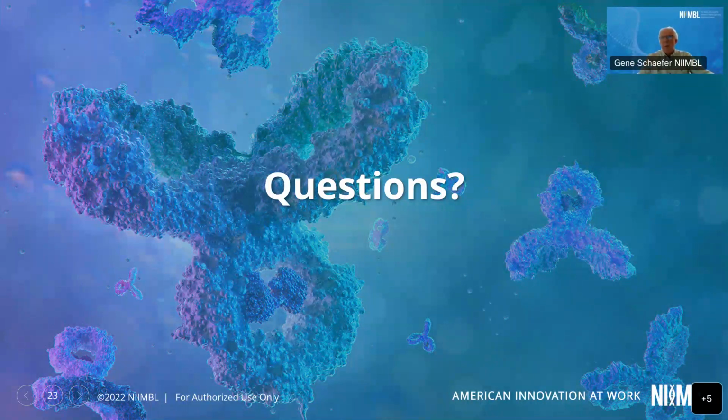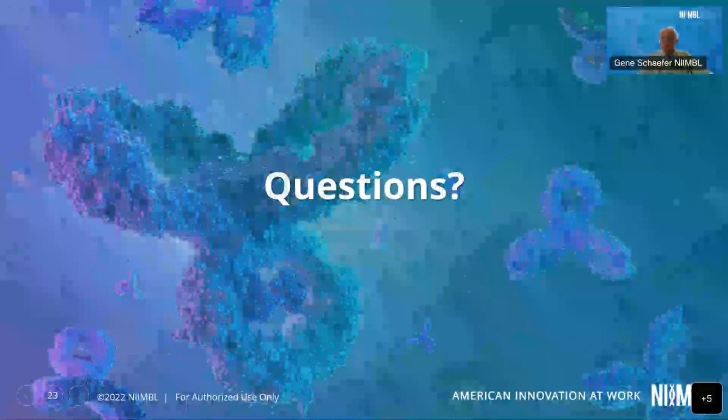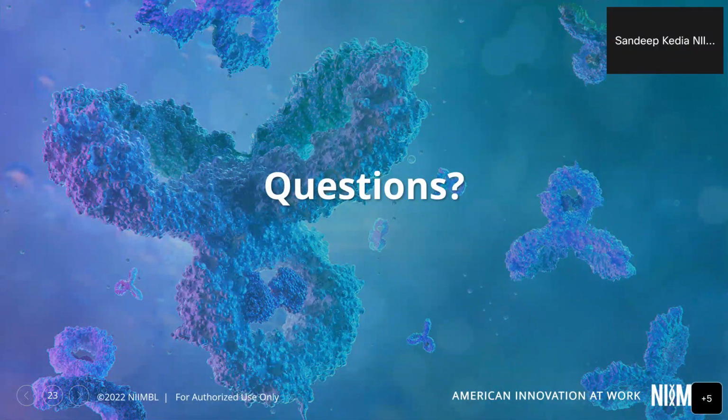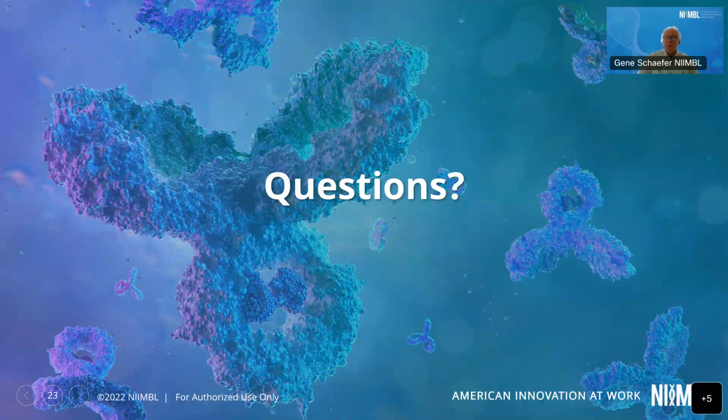And the last point, we did, as I pointed out earlier, look at the other option of just running that as, say, a dual tank alternating mode, where you're essentially running it as a cycled batch operation in the middle of the process. Some of those defaults, similar to cycling between two columns, some of those approaches are good gateways into a more continuous and integrated downstream if you're not ready to have everything fully continuous from day one.